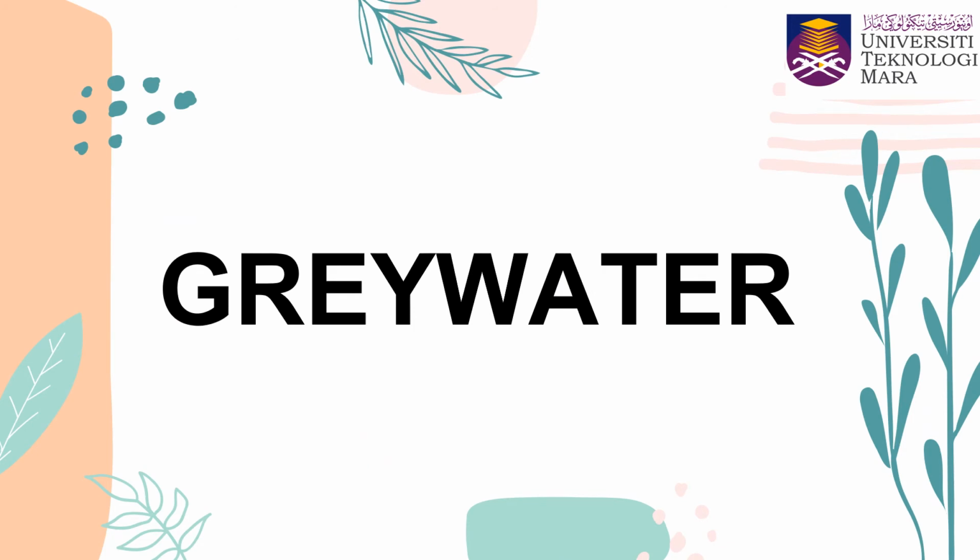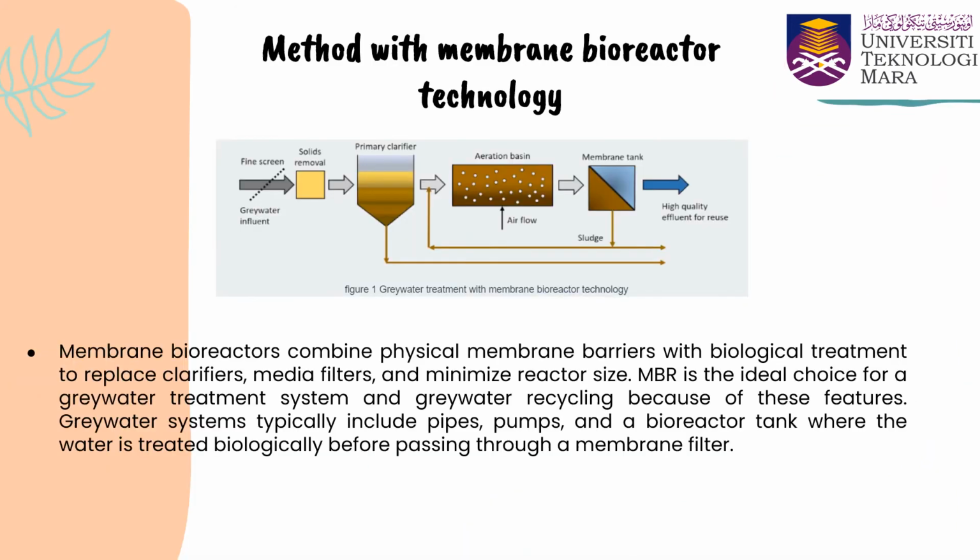And then grey water, lastly. For grey water, we have two methods: a method combined with membrane technology, or the conventional method. The method with membrane technology combines a physical membrane as a barrier with biological treatment to replace the clarifiers.